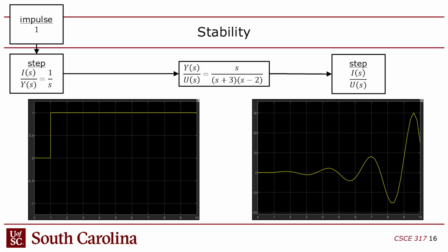So if you want to find the step response, you have to create a transfer function for the step itself, which is 1 over S, and then you multiply that by the function that you want to see the step response of to create a unified transfer function, and that's your new transfer function. Does that make sense? It just blows me away that there's no actual signal input into this other than another transfer function. That's the crazy thing about this.